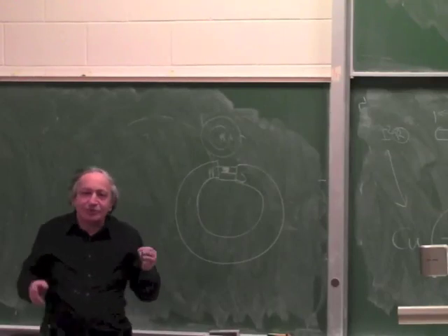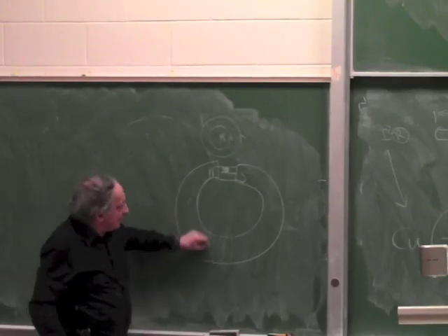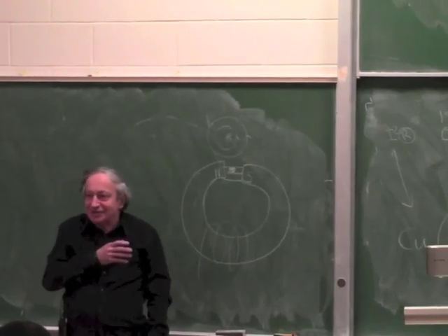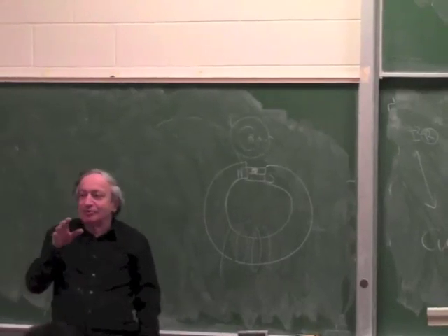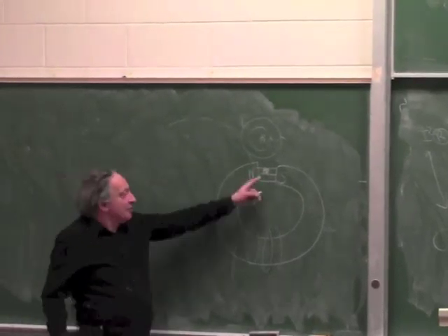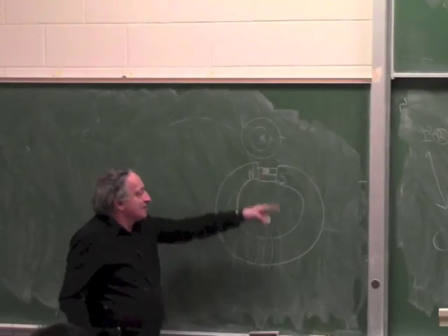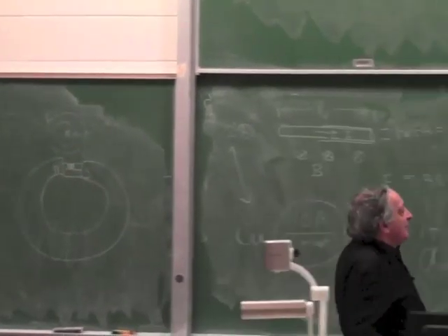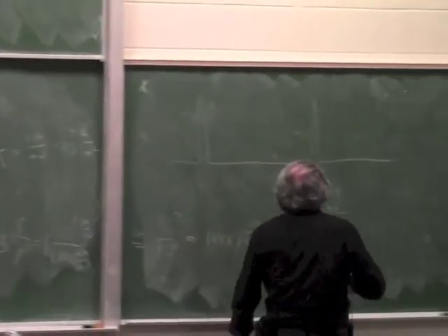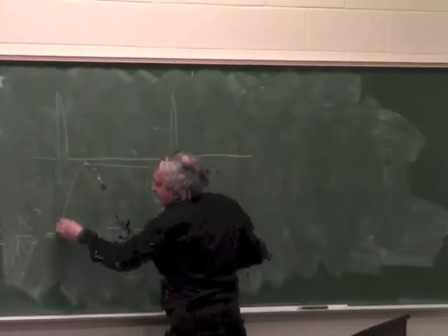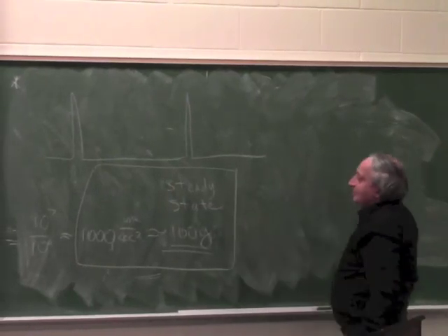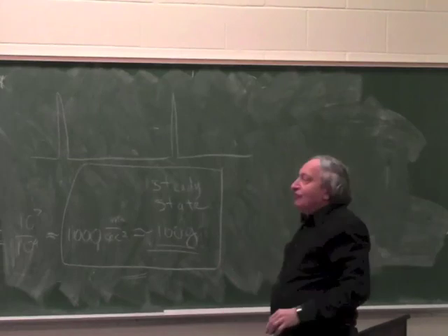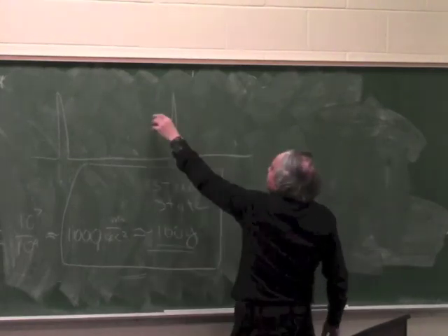If you don't know it, the way you make magnets, you put a big coil around them and send a huge pulse of current. That's how it magnetizes itself. Okay? Well, I'll talk a bit more about it when we talk about moving magnet actuators. But if you put a huge current inside, it's the same as remagnetizing the magnet. So basically there is a second limit, and this is the limit for pulse mode. For steady state, this is the approximate limit. It's easy to remember, 100 G. For pulse mode, the limit is demagnetization.